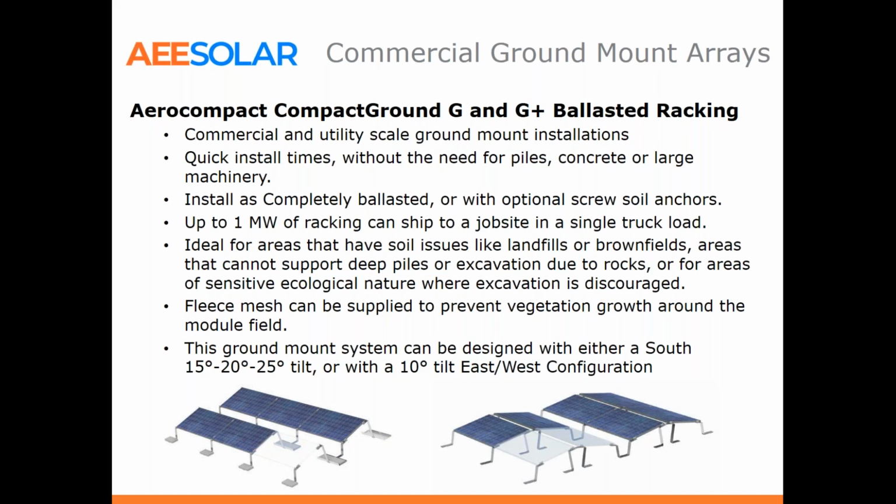Here with the Aerocompact ground mount, you're putting out usually some sort of a landscaping felt on a somewhat flat terrain, and then building your array. And typically you can get a 3-day build down to a 1-day build, just needing the trenching from the array to the point of connection. Up to 1 megawatt of racking can ship to a job site on a single truck roll.